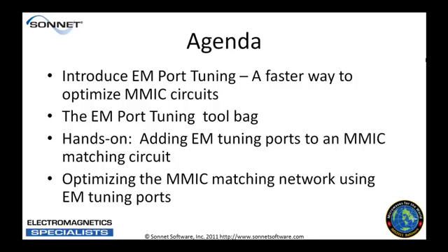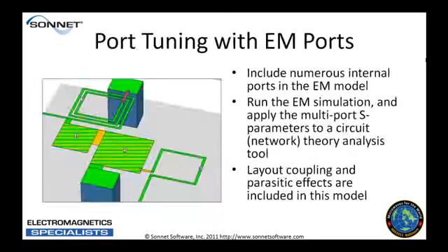Now, we have to start with the introduction of some basic tools that one uses for EM port tuning, and so we'll talk about the techniques that we have in our port tuning tool bag. We'll also do a little hands-on demonstration where we're going to add EM tuning ports to an MMIC matching circuit, and then we're going to take that matching circuit with tuning ports into a popular circuit design platform and show you how port tuning and optimization works.